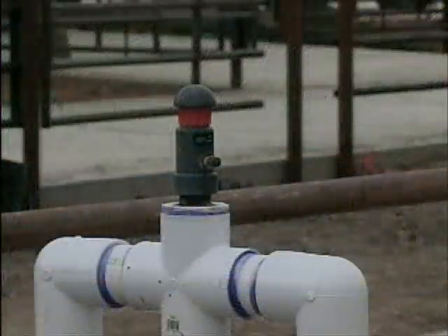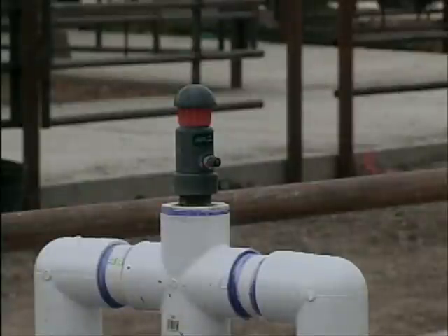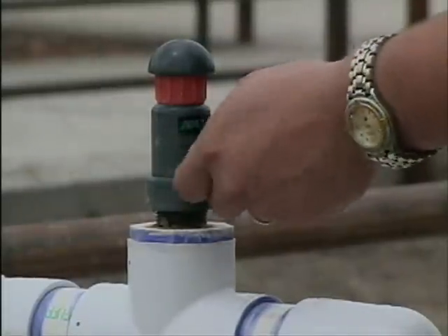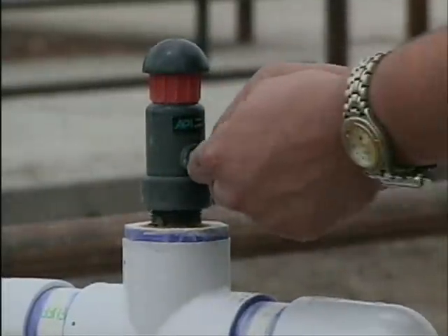The goal is to place the drip laterals as shallow as possible, but prevent wastewater from coming to the soil surface during a dosing event. The inclusion and placement of air relief valves is critical. Valves are installed on the supply and return manifolds at the highest point in the field.